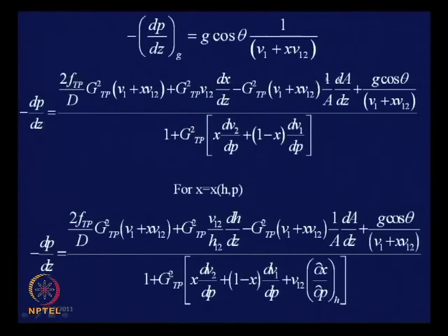And other than FTP, if you observe both the numerator and the denominator, you find that other terms, the pipe diameter, the mass flux, even the quality change with length, can be obtained from enthalpy balance if at all there is a heat balance, otherwise this term cancels off. And the phase physical properties, the taper, if there is a taper then we have this term, otherwise this term also cancels out. So, more or less we can obtain everything else from known input parameters. This we have done for this situation, we have considered there is an area change. Any doubts you want to ask?